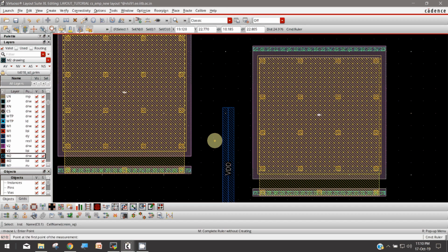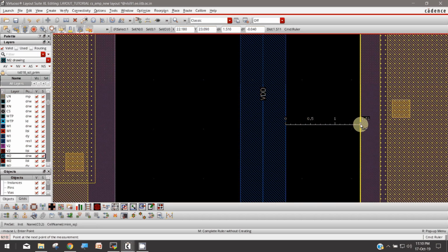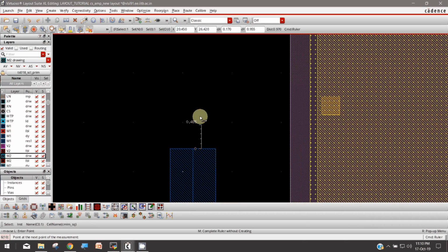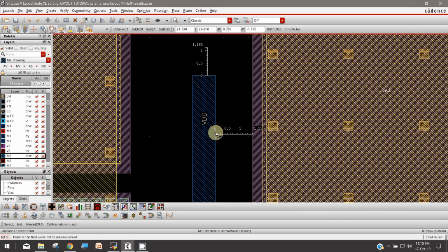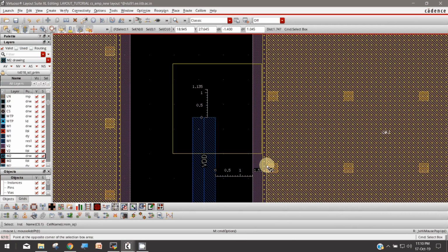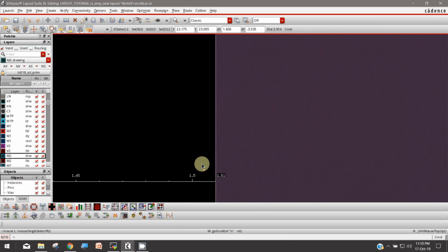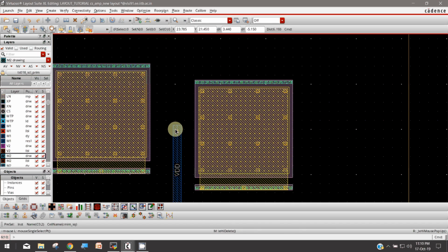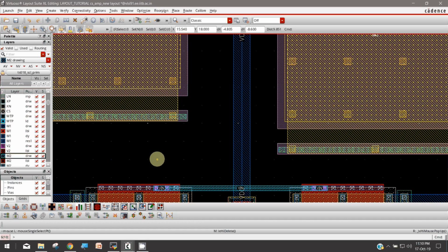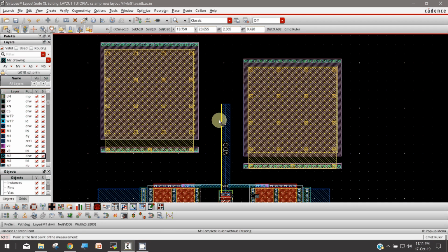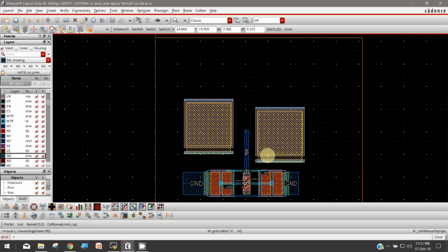So when you go to create measurements, you can create scales to measure. Suppose you are very much stuck in a very minimum area and want to clear DRC rules or want to accommodate something, you can actually measure things very neatly, and this will be very accurate, and then you can place them. One use of this is to maintain symmetry and other things, like you can measure the distance between these. It is not very symmetric, it has some changes. Similarly, you can arrange things symmetrically.